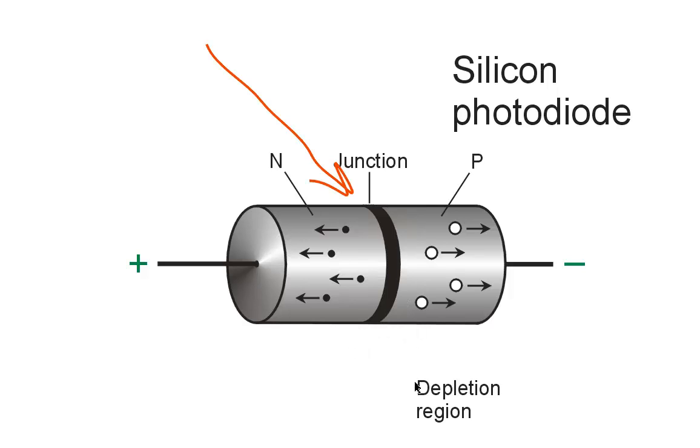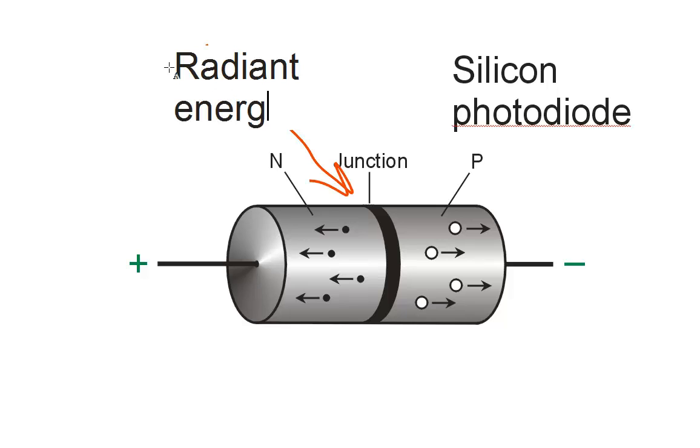When that happens, the diode conducts, something like the avalanche effect, except it conducts to an extent that varies according to the brilliance. Well, radiant energy, referring to visible light, ultraviolet, or infrared. The brilliance or the intensity of that radiant energy affects the extent to which this device will conduct. Well, what is that phenomenon good for? Well, it acts like a variable resistor, in effect.